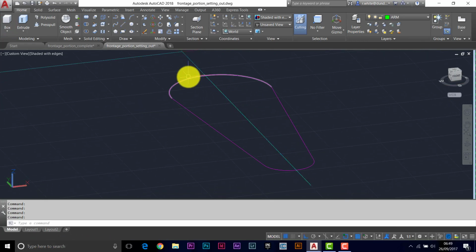So instead of allowing this curve to be extruded as in the previous version, we're going to take control of the curvature here. So I'm going to divide each of these curves. Now, they don't have to be divided by the same amount because they're different sizes. Okay, so we want the segment length to be approximately the same. Okay, so 18 divisions here and 12 divisions here should achieve something like that.